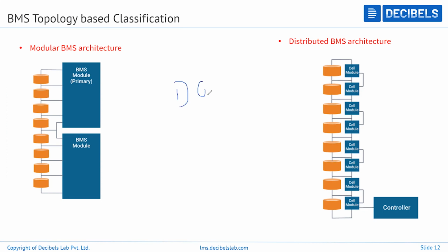Yeah. So when we talk about topology, we divide one into centralized and modular. If you have modular type battery packs, obviously you are going to deal with master and slave BMS. Again, in the modular, there is a series type and a parallel type. Right now in the market, for two-wheelers, all are concentrating on the series type itself, because they are not concentrating much on the parallel type because of a lot of difficulties in bringing it into practice. Okay, yeah, and then the distributed, yeah.